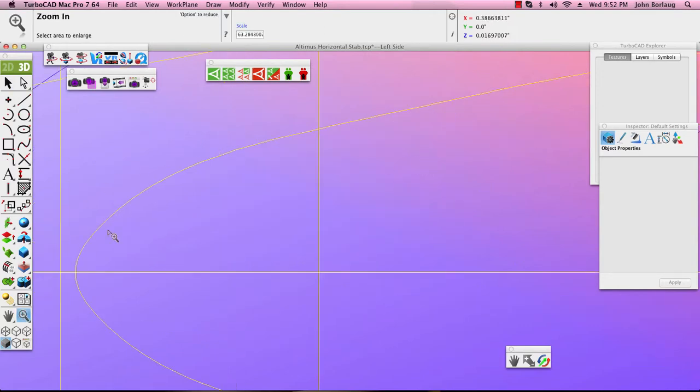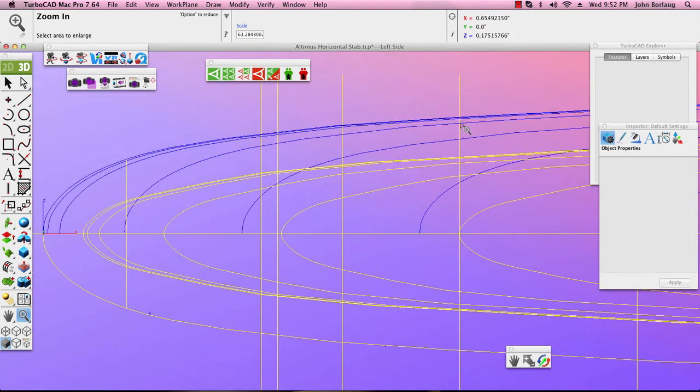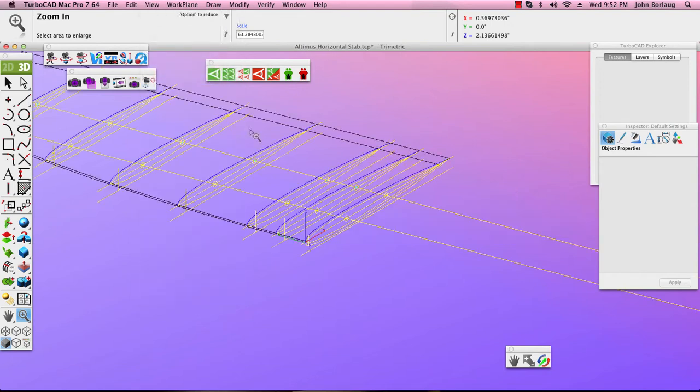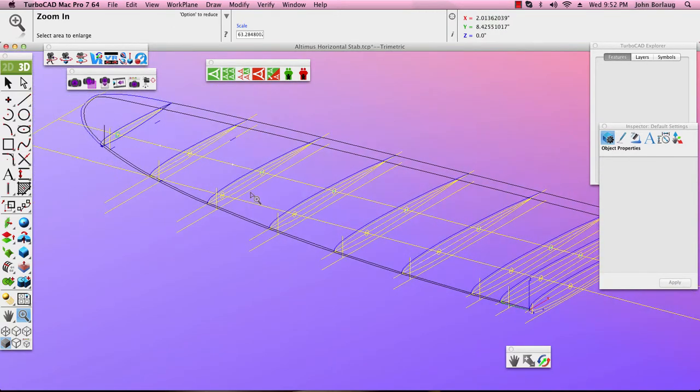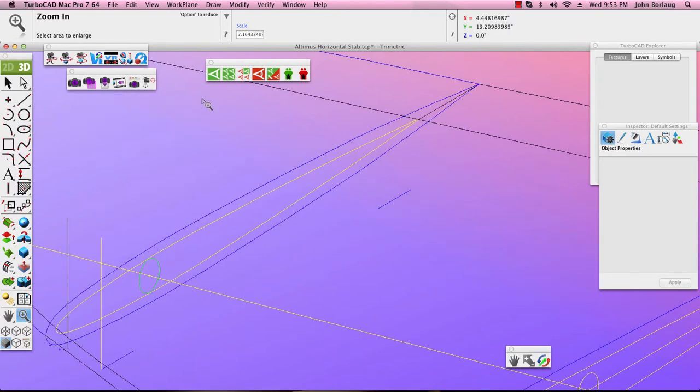And so I basically got rid of all of these lumps and things that were not going to play nicely. And then going on into a trimetric view, what I had done was after I converted that to a line, I scaled that line on each rib location and then ran the guide skin this away, which was grabbing all of these surfaces and then using the two outside lines as a guide, and then a 2-rail sweep grabbing our mirrored data out here.